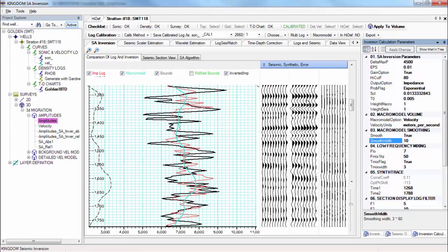The most important inversion algorithm parameters to tune are the EPS and T0 parameters. Guidance is given as to their ranges in the tooltip area below the parameter bank. T0 is the initial energy given to the SA model, and EPS is the convergence tolerance. The key is to balance keeping a good result and getting a sensible runtime.